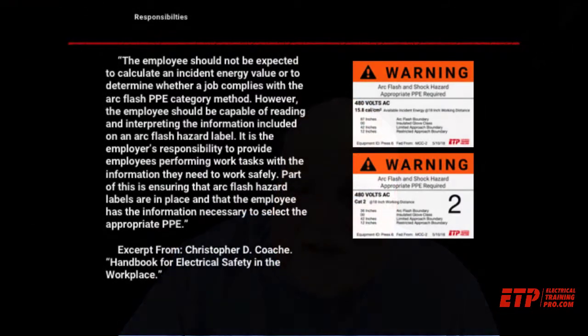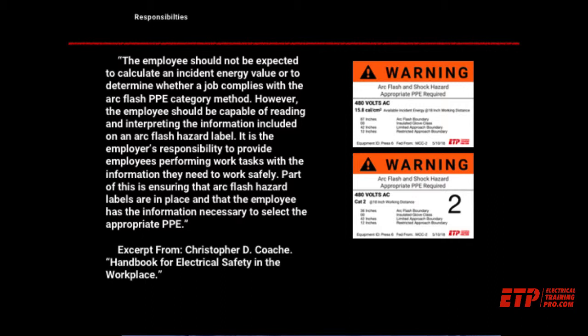The employee should not be expected to calculate the incident energy value or to determine whether a job complies with the arc flash PPE category. So it's not the employee's responsibility to figure out what the incident energy rating of that piece of equipment is. It's not the employee's job to figure out what the category rating of that equipment is. It's the employer's responsibility. The employee needs to know how to read that label to determine what PPE to wear. It's upon the employer to figure out what that arc rating or incident energy rating is. It's on the employer to figure out what should be on that label, not the employee.